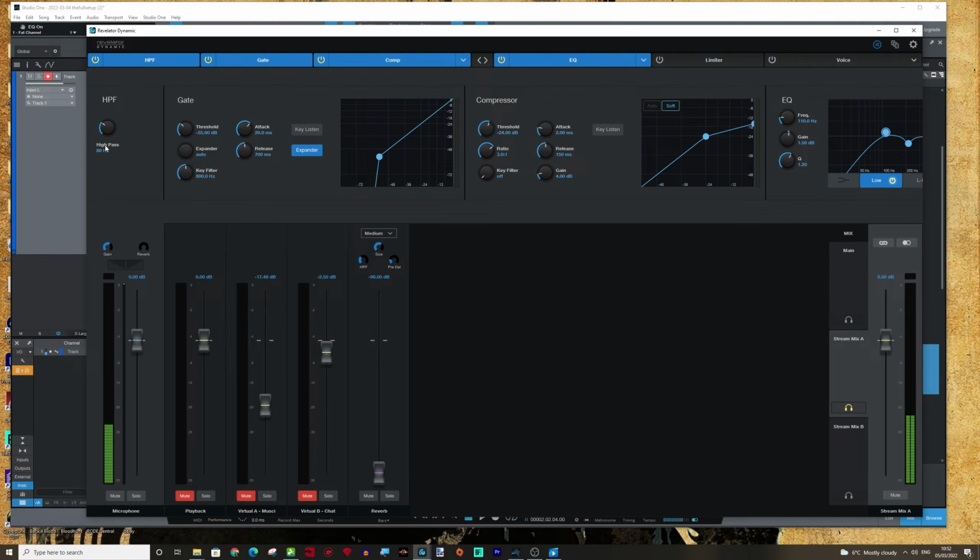Okay, then over to the Fat channel. Now, the most important thing before you're doing the Fat channel is to make sure you've got your gain set correctly, okay? So you ideally want your peaks to be coming around here. As you can see, I'm not quite there, so maybe the -10. But you can see there, that is where I'm coming up. So if my general talk here, that's coming somewhere between maybe -22 and -15, was actually higher up here, then when I said a 'b', it would end up being very much up here, and we could come close to clipping. So your gain is going to be somewhere between 36 and 42 dB, okay, depending on how you talk. So you want to get that set correctly.